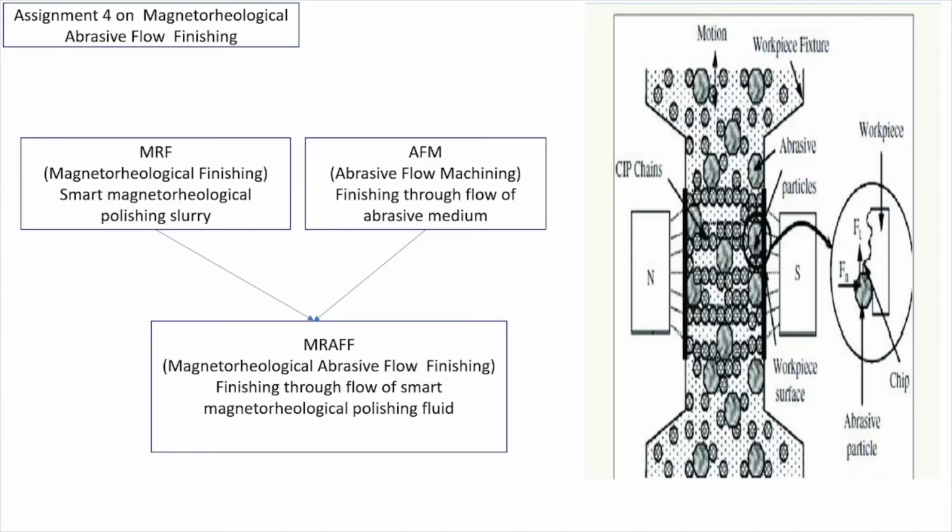By applying a magnetic field, the viscosity of the material can be increased or decreased, controlled by the strength of the applied magnetic field. The fluid can shift from liquid to solid, and from solid back to liquid, quite quickly. This makes the material flexible, allowing it to adapt to external forces, so viscosity and all rheological properties can be varied.